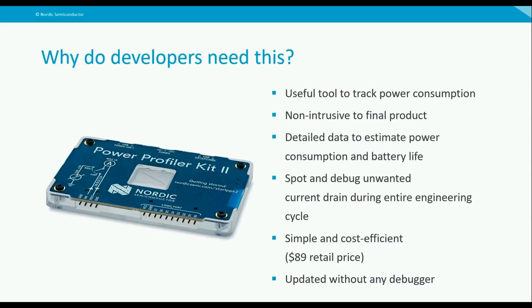This will also save you time, as you can debug unwanted power consumption right away, instead of waiting until you have taken your time to see how much better life you can expect out of your product. It's also very cost efficient, seeing as one does not need an extra Nordic DK or debugger to communicate with the computer software. And yes, the PPK2 is supported in Windows, Linux and macOS. When updates to the PPK2 firmware are needed, the software will take care of this through the PPK2's bootloader, so there is no need for an extra programmer.